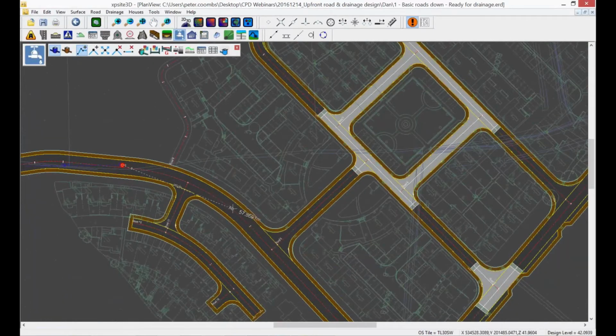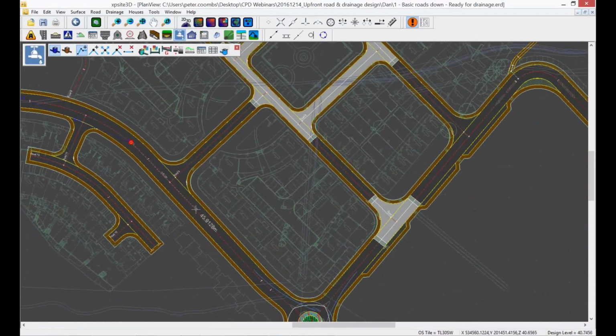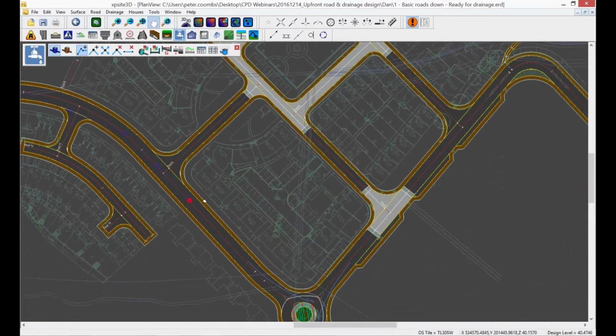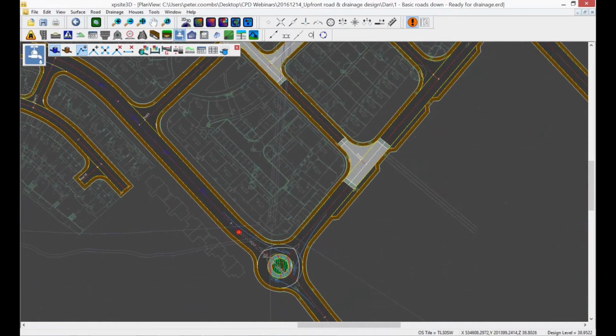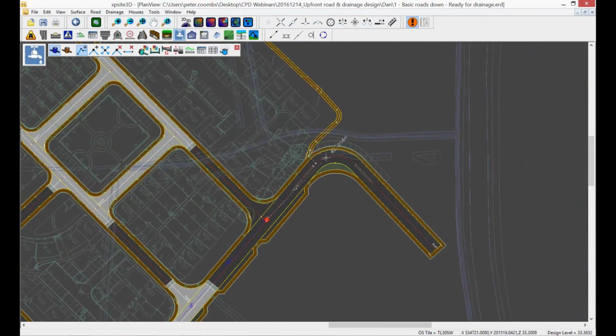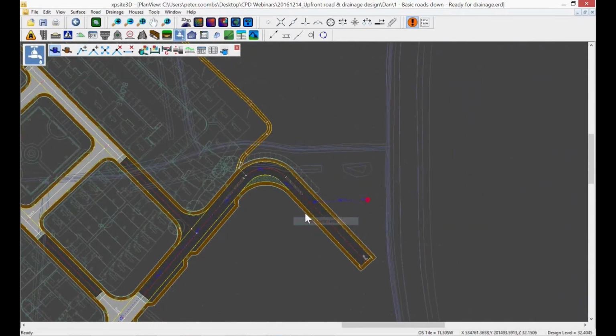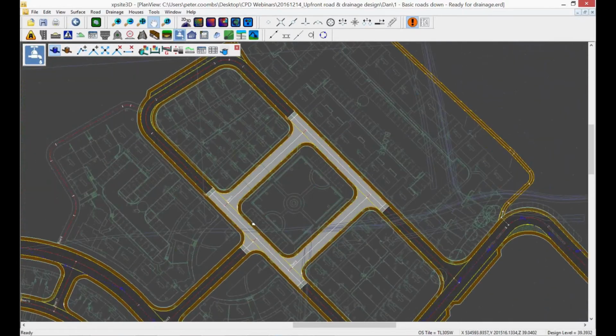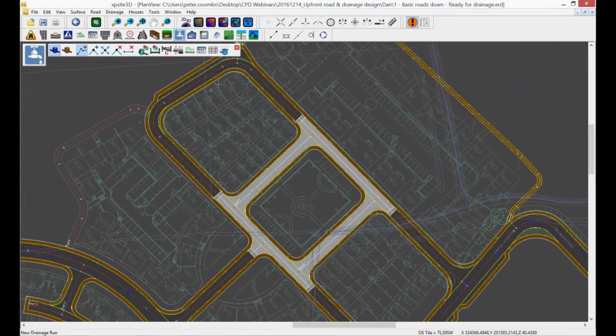I'm just going to follow from west to east, which I've been instructed by Max. We've got a very steep site, so let's take that into consideration. I'm going to show you putting manholes at each junction on the road. We don't want to go under the road. We want to keep the cost as low as possible and have the outfall coming here. I can just quit that off. Very quickly, I just want to show you how you add in an extra run